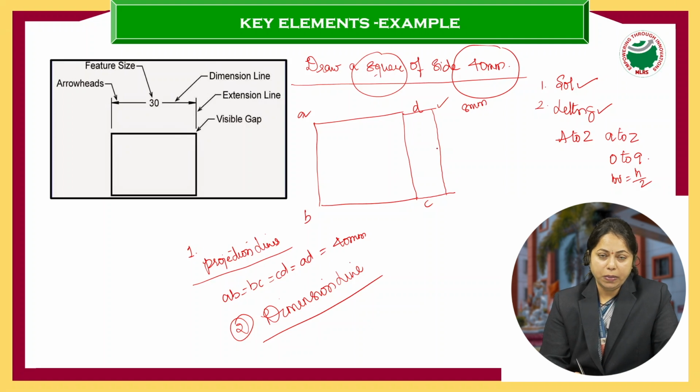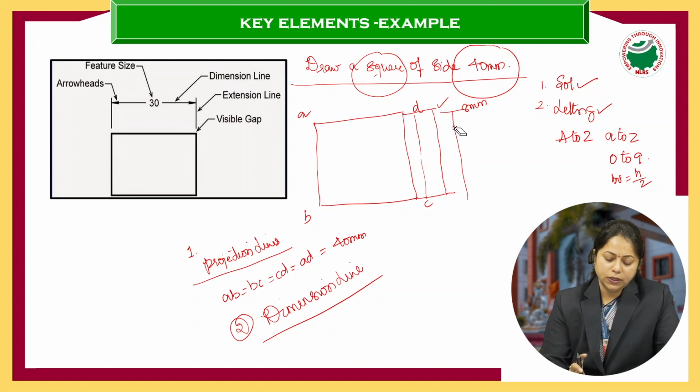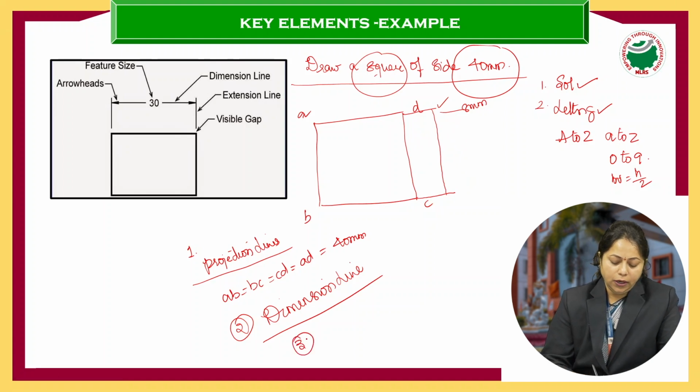You know, this has to be parallel. What should be the distance? It should not be too close and it should not be too far. Here also the distance can be maintained as 8 mm. And the third one is arrowheads.